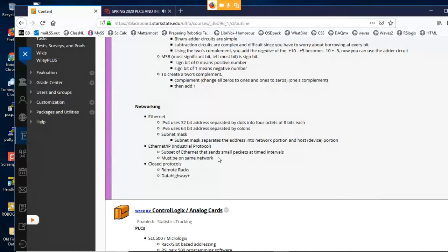All right. And the most common one that I'm seeing in any new equipment, they really tend to be pushing this Ethernet/IP. Part of that's just because everybody understands Ethernet IP pretty well nowadays, especially IP version 4. Plus, if you need a switch to plug in multiple devices, you can buy a switch very cheaply. You can get a pretty reliable switch. So people have been moving that way. There's a lot of DeviceNet and ControlNet out there, but you're seeing a lot of the new stuff go to Ethernet IP.